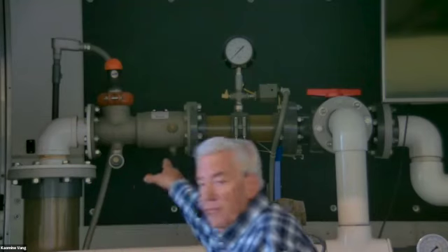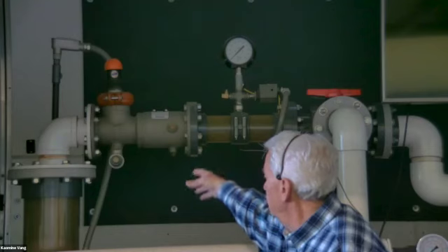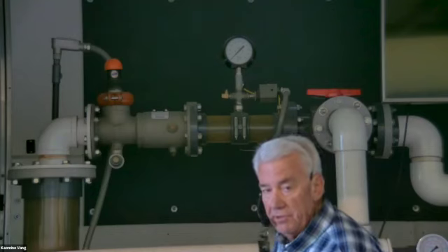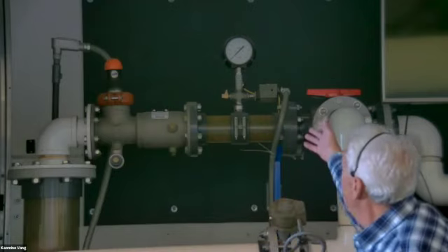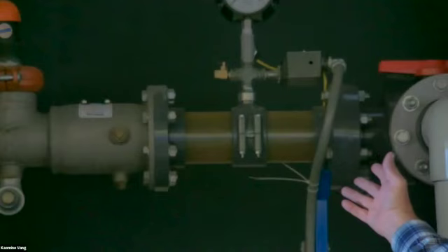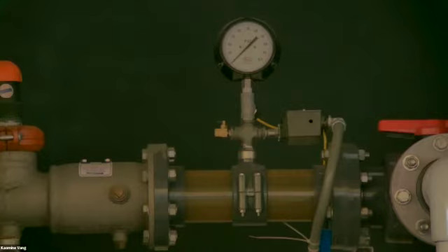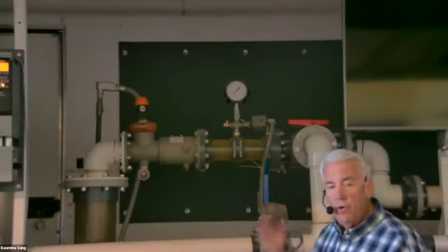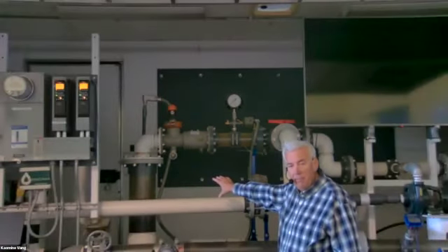Water comes out of that. We have our chemigation valve, so backflow prevention, low pressure drain, air vacuum relief vent, and single mainline check valve. You have to have those in agriculture if you're injecting fertilizers or pesticides. We have our pressure gauge here with a transducer. That transducer takes the signal of pressure, and when I have this pump running, you'll see the pressure reading. You multiply that by 2.31, and that gives you feet of head. So we'll see how many feet of head are coming out of this pump.